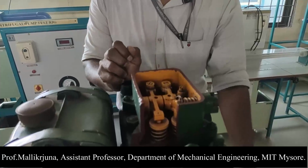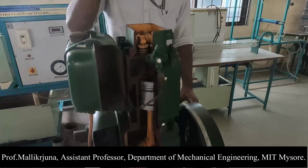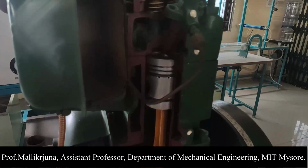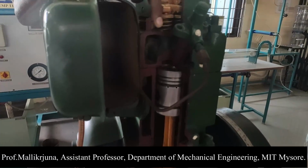Exhaust valve is also not moving. Now, if you clearly observe, the piston again reaches the TDC. That means two of the operations are over. First one is suction and the second one is compression.